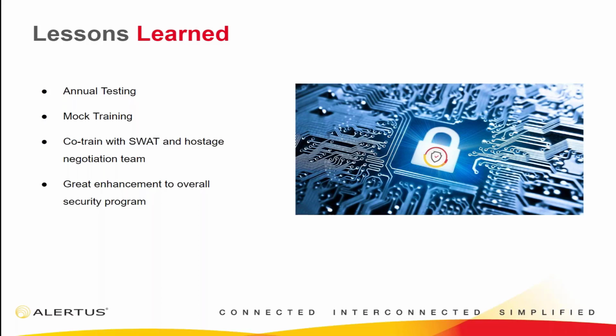Next question here. How does the alert beacon interface with a voice fire alarm system? With a voice fire alarm system, as I mentioned before, we have two ways in which we can leverage the fire panel interface, one of which being that verbal alert over the speakers that are already being utilized within that fire panel itself.